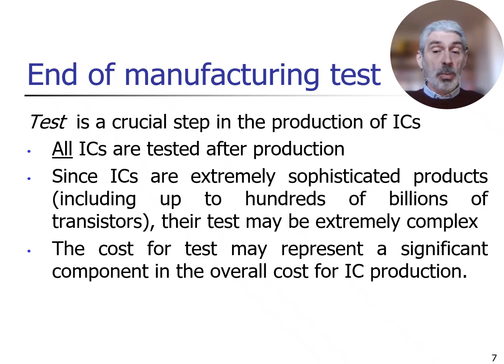Here you need to check whether every transistor inside the circuit works correctly, every connection has been manufactured correctly, and so on. You need to test everything. For this reason, for this complexity, the cost for test today may represent a significant component with respect to the overall cost for IC production.